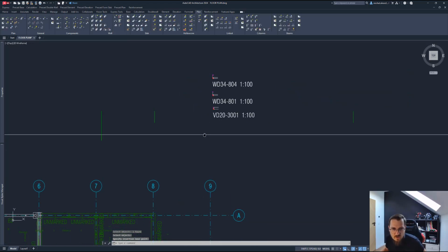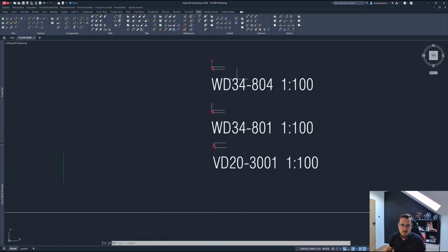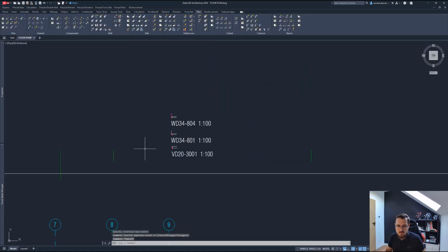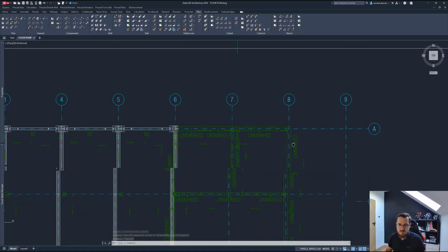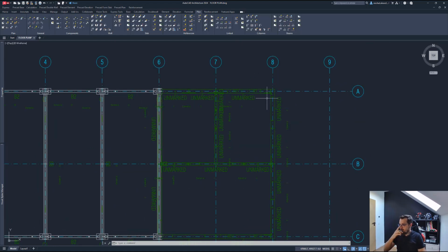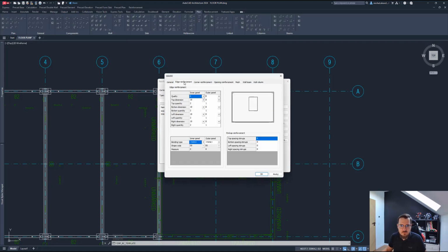Now, whenever we create drawings for our elements, if they contain any of those end caps, then this reinforcement will be applied. I could delete that from the model right now. It's no longer needed. It's saved in the database. That's it. It's saved. But what I would like to do right now is show you the reinforcement templates, right? Because let me go and accept those, and that's reinforcement.